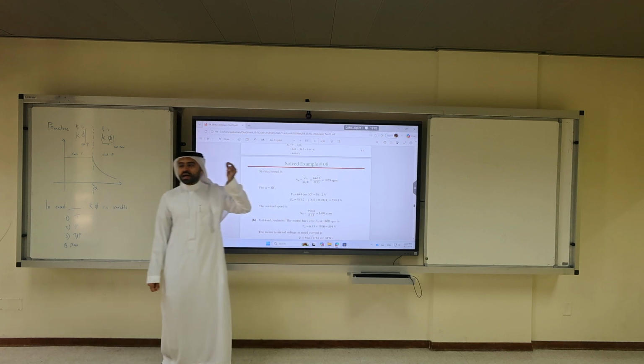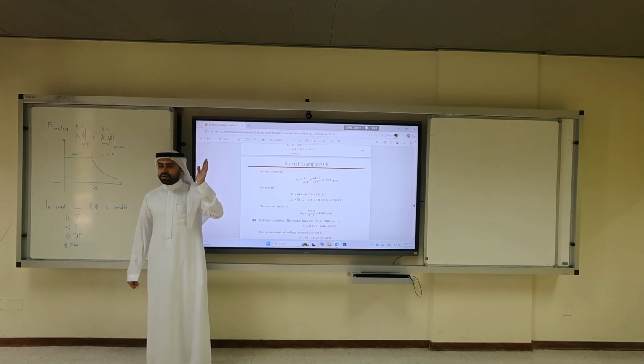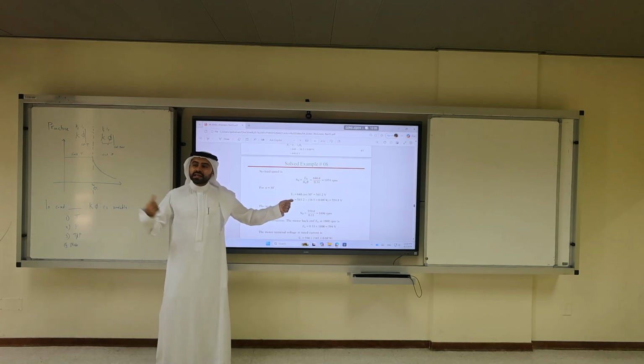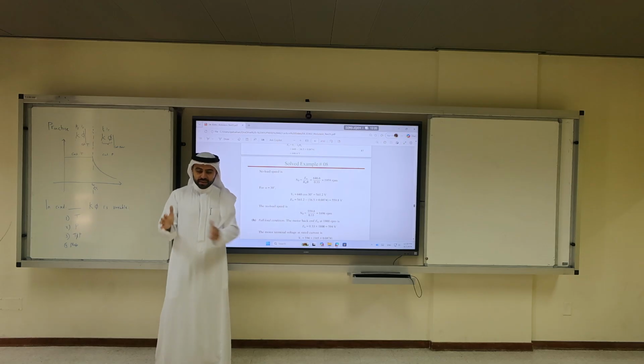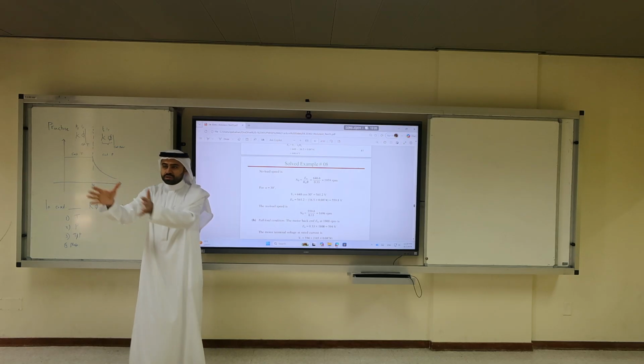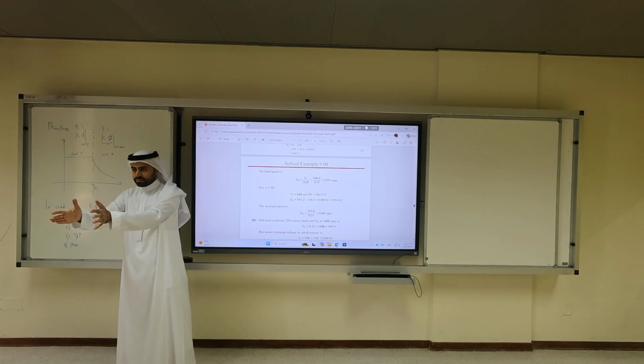So what do we understand? For firing angle from 0 to 30, the speed will drop. And this is how we control a DC motor from an AC power supply. Remember, there is a box between the supply and the motor, which is the AC to DC converter. Okay?